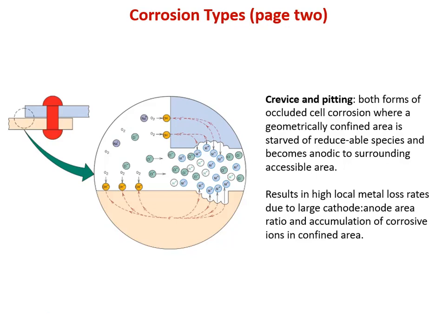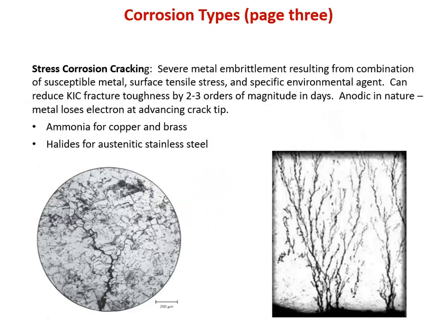There are other things that happen chemically down in that crevice that keep this going and actually accelerate it. As those metal ions go out into solution, they have such a high charge density, they will acidify the solution locally, making it harder to passivate and shut down the reaction, and actually attracting, by ionic electrostatic interactions, other aggressive species that keep things going. So corrosion pits and crevice corrosion is often described as being autocatalytic, and it's very deadly, especially if you have something like a pressure vessel or a pipeline that you'd rather not have a hole in.